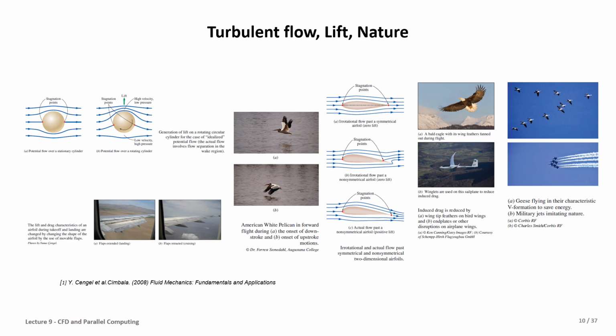Also, there is another example of the flap of the wing of the aircraft when it's activated and is making a different effect on the lift of the aircraft. In the middle of the slide, you see an example of the airfoil section, which has a different angle of attack, and the stagnation point has a different location. It makes different lift force, and also it's about the drag, and you can have control of this section.